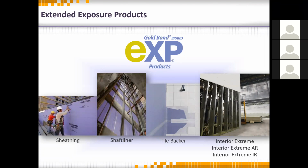So you need a fiberglass face product in there if your people have to hang drywall so that they can do MEP work. Now, once the building gets closed, you can install the rest of the drywall and do your finish out of that. So it's important to note that if your building hasn't been closed and it's not conditioned, you need to use a fiberglass face gypsum. We can talk to you more about that later.